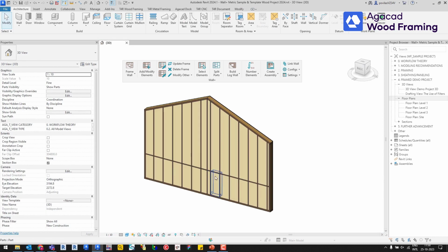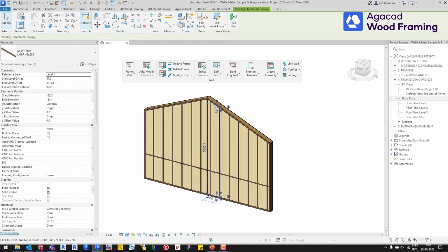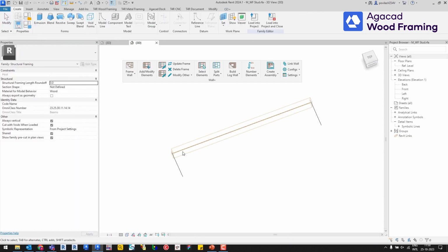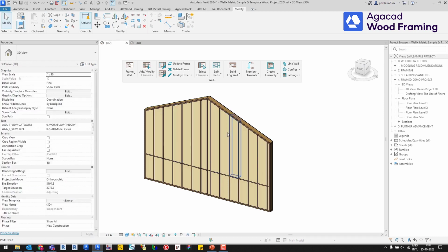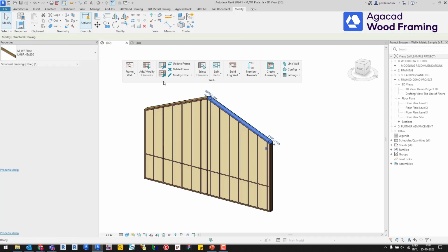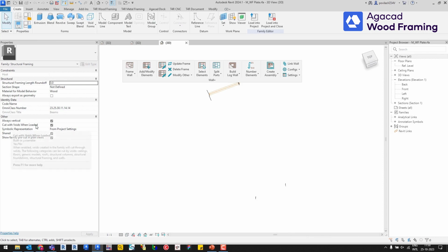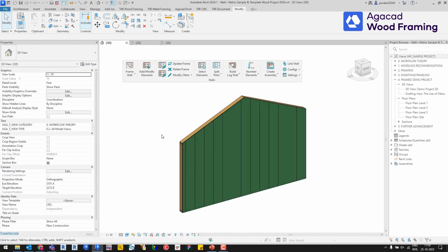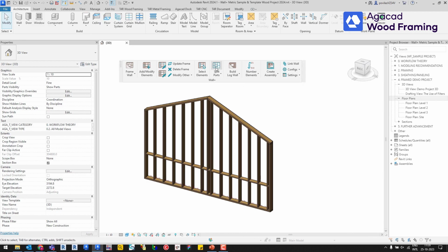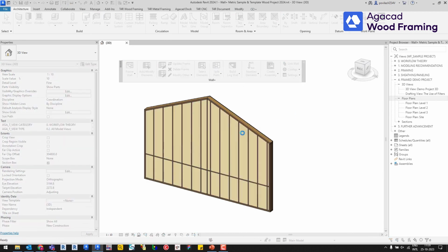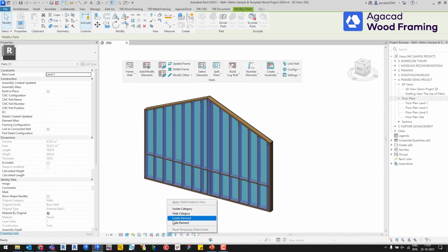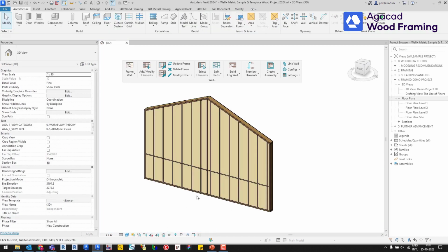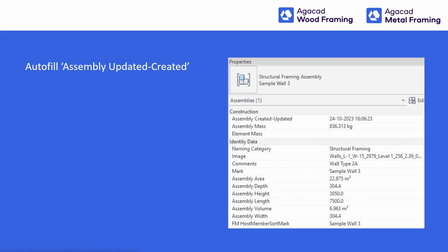So that's something you were kind of able to do that before, but not really as convenient and not really as thorough. Also keep in mind you have cut with voids when loaded checkbox on for your studs and plates. So this option will help you to actually split Revit parts. But you have it on, you have the split parts type parameter for your studs and plates on, and then you adjust the paneling configuration like you've seen previously, and will automatically split your insulation based on your vertical and horizontal elements.